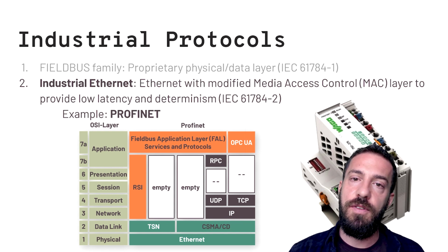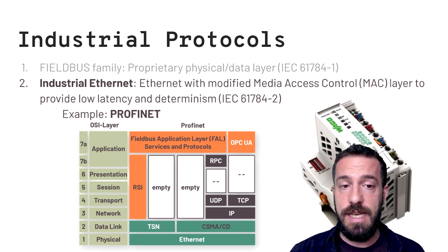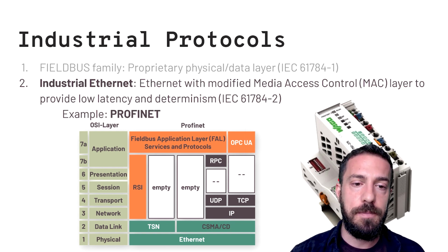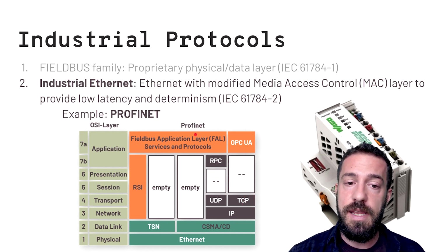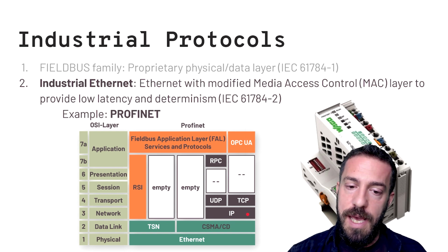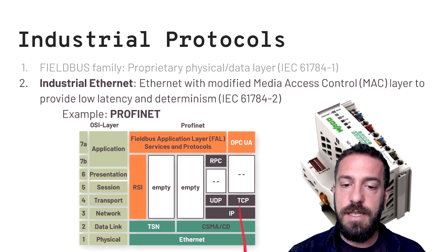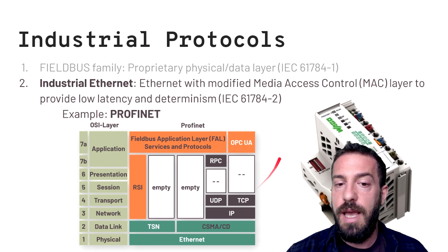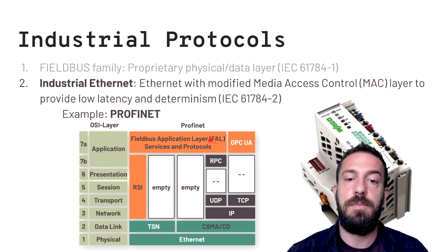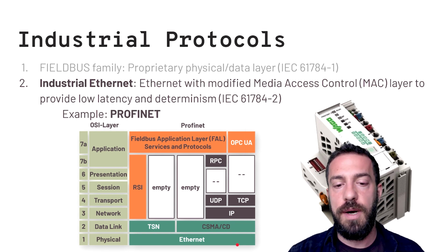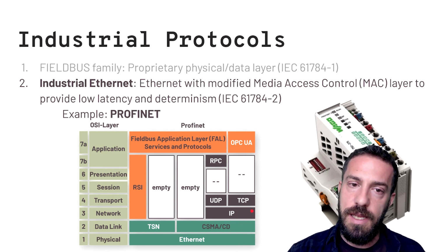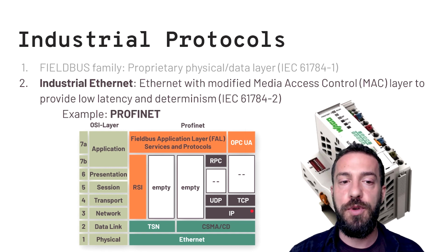Because Profibus from before could support only up to 127 devices. Here, you can support as many as you want, given that the Ethernet protocol is in place. And also you can have a version of it that is also over TCP/IP. So you can have the application protocol over TCP/IP over Ethernet. So here, this is how our computers also work. We have our regular computers, HTTP connection here, and over TCP/IP over Ethernet if we connect through wire to our router. So we're getting closer in the protocol side to also how our computers work.